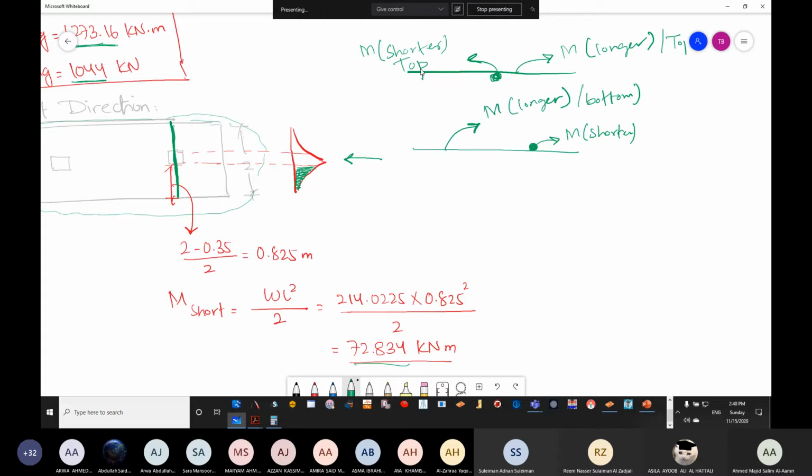Okay, so the bigger problem is going to be in the matter of one-way shear and two-way shear, since we didn't discuss it. Now I tried to completely finish one problem in terms of bending moment and calculation of reinforcement for the isolated foundation, and then we have done the same for a combined foundation. Now what I'm going to do is return back to the isolated foundation to work out the one-way shear and two-way shear, and then we'll return back to the combined foundation to check how to calculate the one-way and two-way shear.